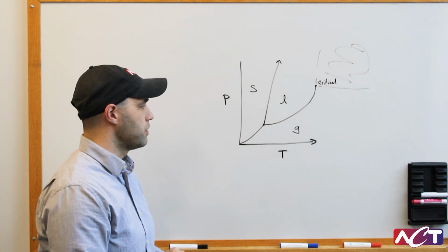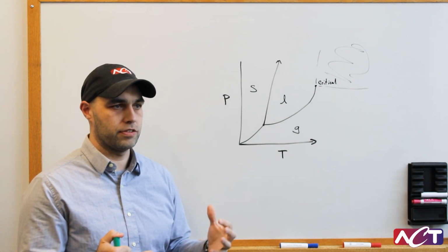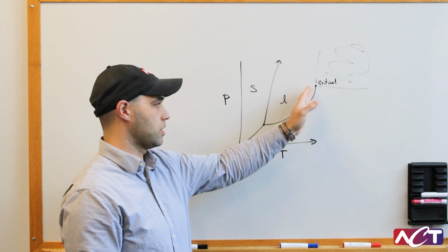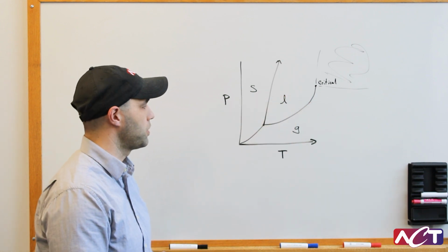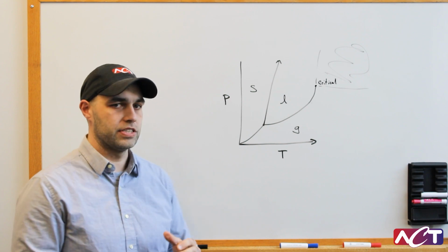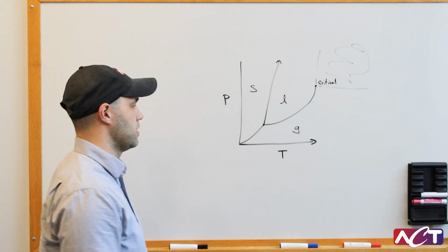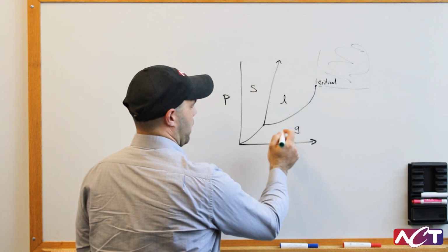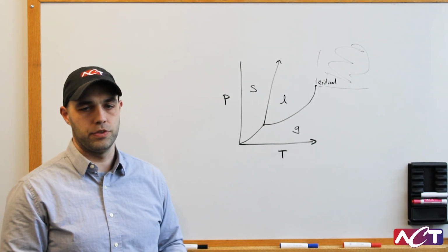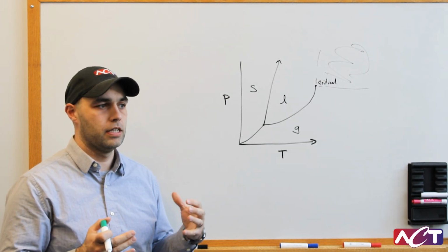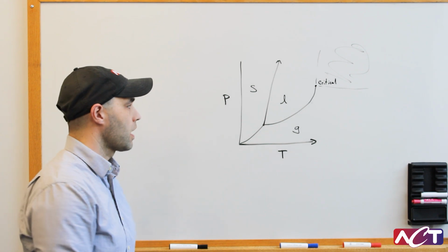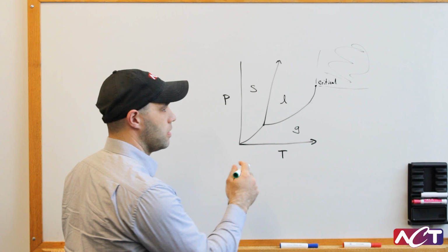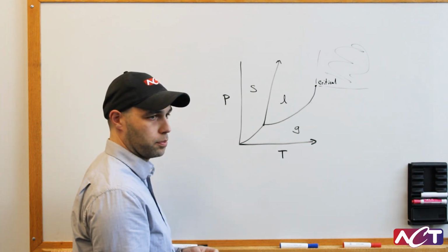A couple of those reasons are, one, heat transfer coefficients. Heat transfer coefficients are typically better when the operating pressure is closer to the critical pressure. And the second reason is due to a controls application. This curve tends to get steeper as you move out, and pump two-phase applications are often looking for very precise control of temperature. In order to do that, it is easier to measure and control pressure.